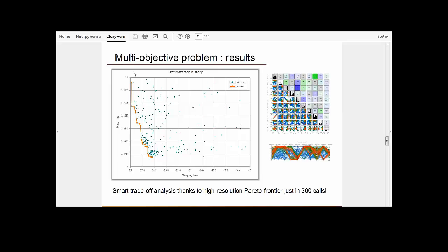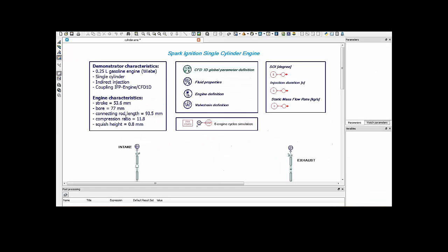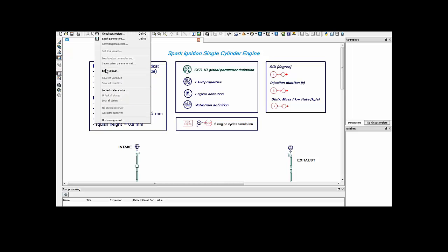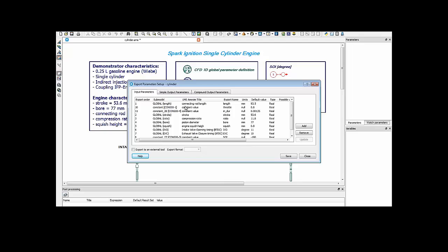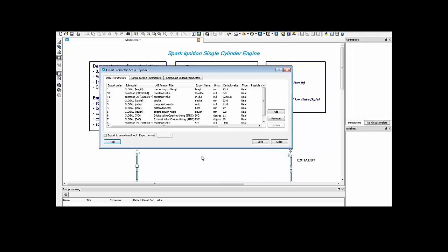I want to know the process of how you generate the Amesim input template file. The Amesim is quite a powerful tool for study. When we set these export variables, the variables that we can control from outside, these files are created automatically. There will be two files for the input parameters list with these export names.